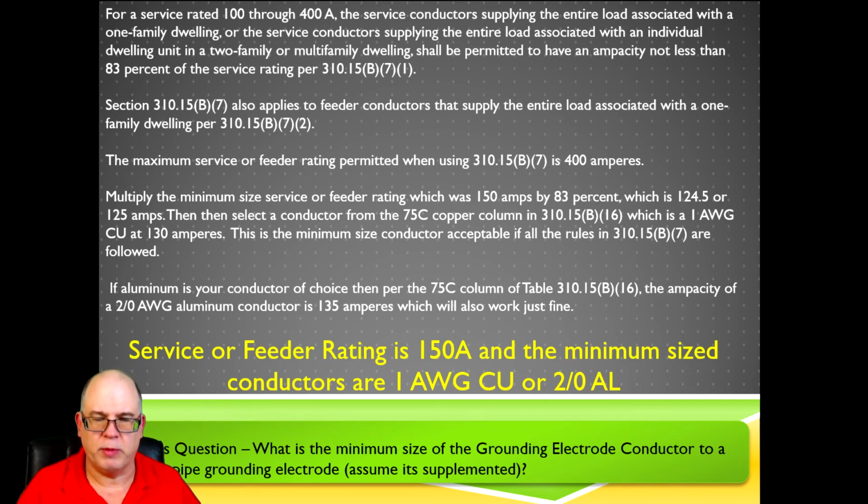The code tells us we can do that. All right. Now, most wire today, THHN, THWN-2, that -2 means it's 90 degree rated insulation. Okay. Wet or dry. If it was just THWN, it would only be 75 because it only has one H, so that means it stays in the 75.